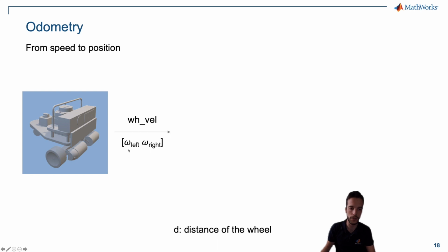In particular, the encoder provides us the angular speed of one and the other wheel. The first step is to transform these two pieces of information into the linear and angular speed. To do so is easy. We can use the previously developed module, the kinematic one, and this module simply transforms the angular speed of the two wheels into the linear and the angular one.